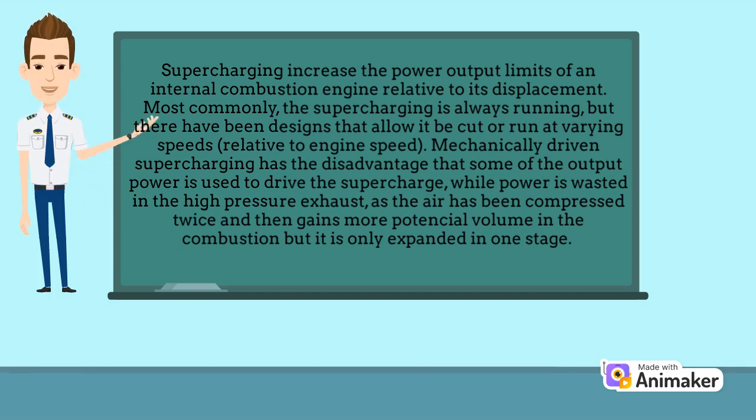Mechanically driven supercharging has the disadvantage that some of the output power is used to drive the supercharger, while power is wasted in the high-pressure exhaust, as the air has been compressed twice and then gains more potential volume in the combustion, but it is only expanded in one stage.